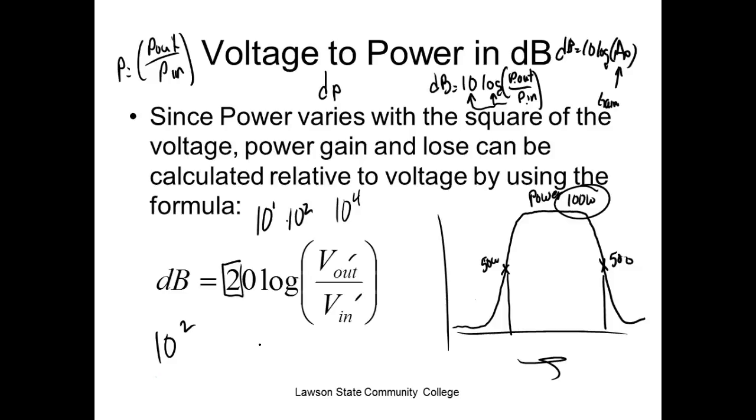You understand? Yes or no? Well, you're not doubling it. It's a power of 10. So if I go from 2 to the first to 2 to the second, am I doubling? So if I go from 2 to the first to 2 squared, that would be what this is, because this represents this right here. So when I multiply by 10, I'm using the actual number. If I multiply by 20, I'm squaring that number, right? You understand? Because you have to represent it. Think about bels. If I go from 1 bel to 2 bels, I've squared the number, right?